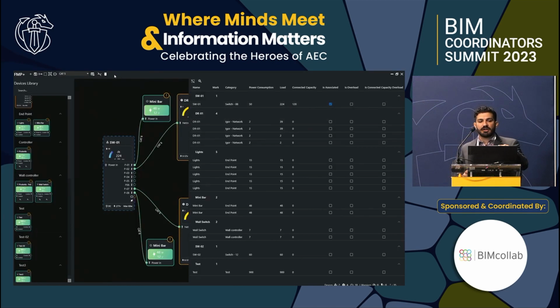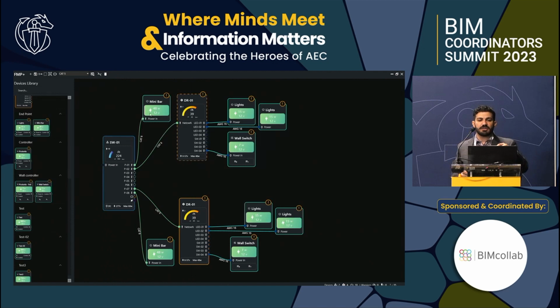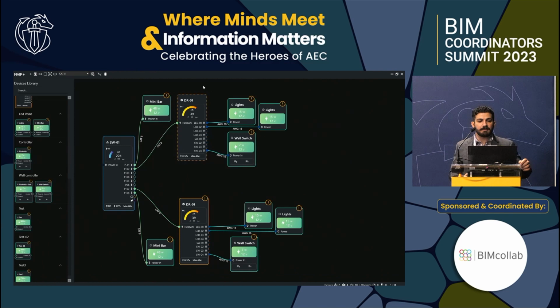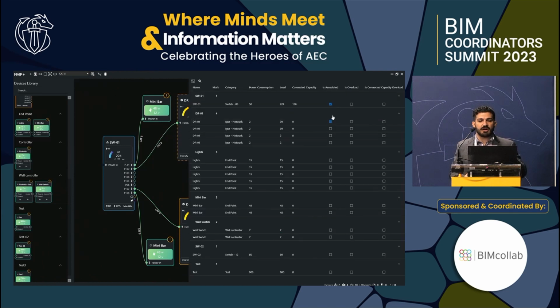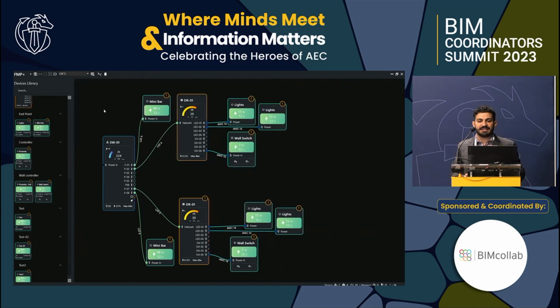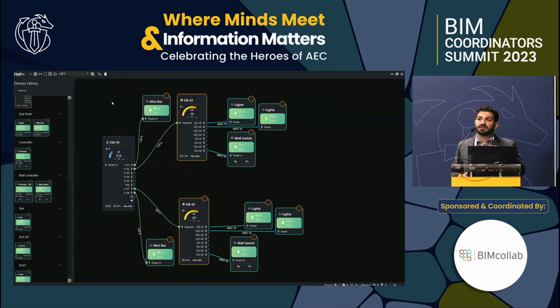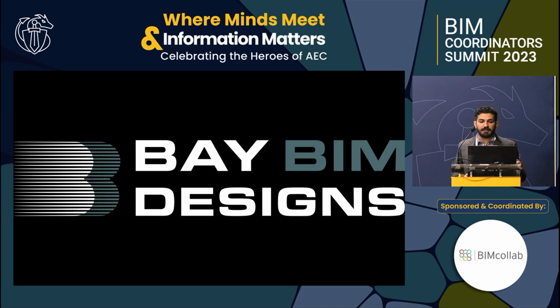As you can see on our material list, it's been associated. I'm doing the same thing with the driver now, and the exclamation mark is gone. I can see on my material list that it's gone. And if I select it and click the search, it will zoom in Revit to show me exactly where that device is within my layout.